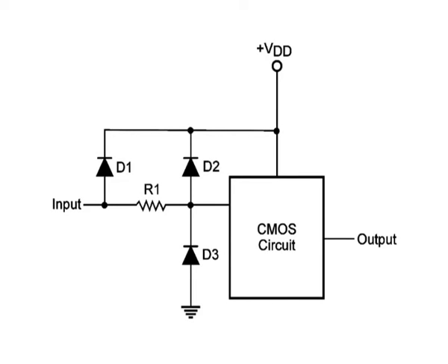The protection circuit shown is typically used in metal gate MOSFETs such as those used in 4000 series CMOS devices. Diode D2 limits the positive voltage surge to VDD plus 0.7 volt, while diode D3 clamps the negative voltage surge to minus 0.7 volt. Resistor R1 limits the static discharge current amplitude and thus prevents any damagingly large voltage from being directly applied to